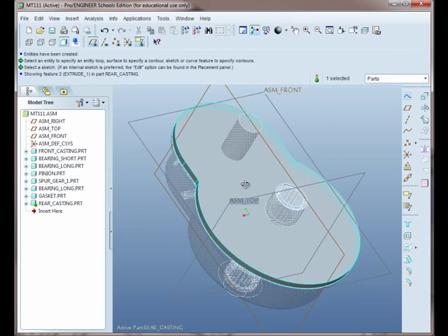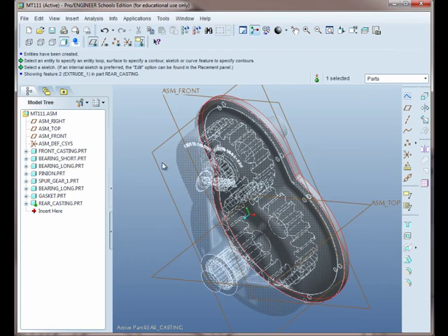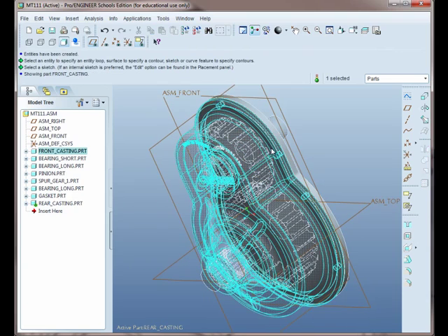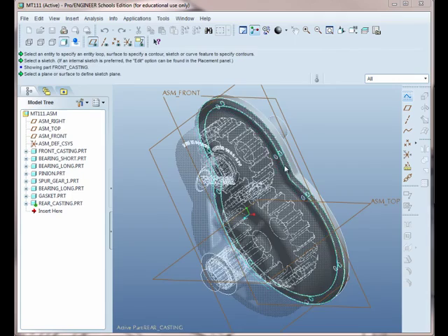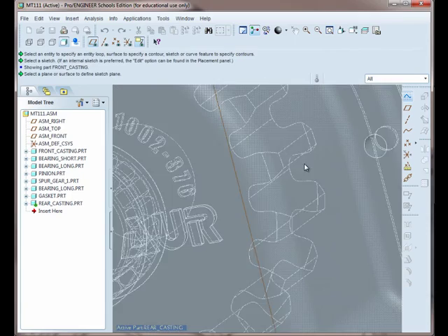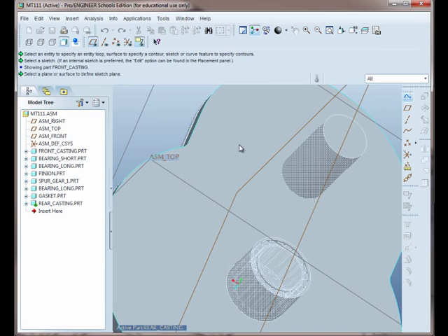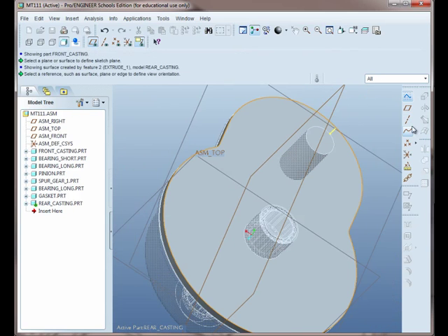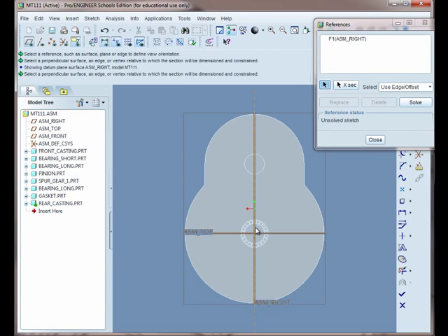The next thing I'm going to do is select this backside face to start constructing the rest of the model. Let's go ahead and go to Sketch, and again I could just click on that backside face, or I can select this face too. That works. Start a sketch. Again, for the references, you can select the vertical and horizontal plane.